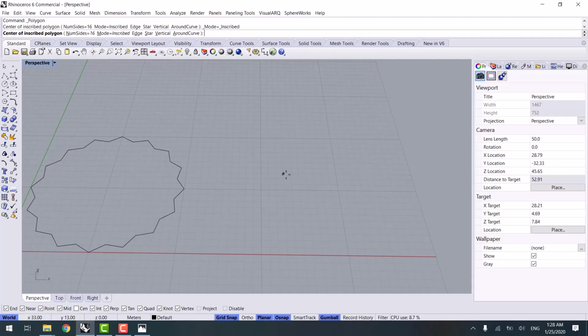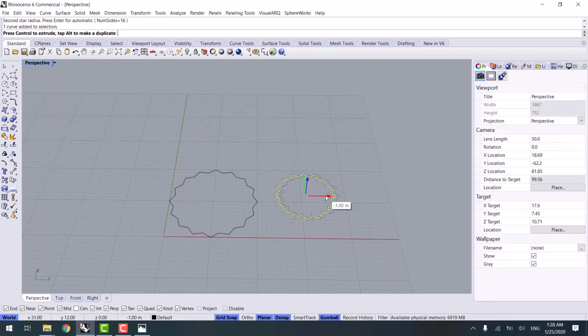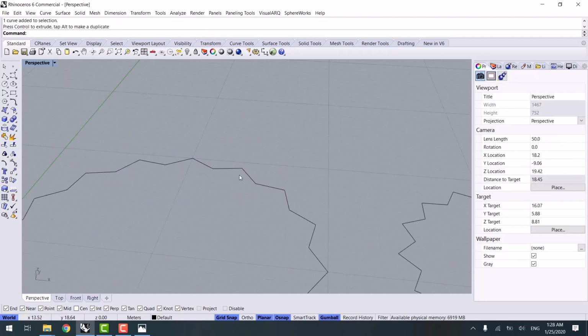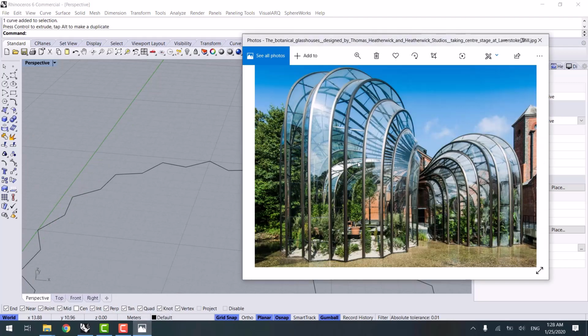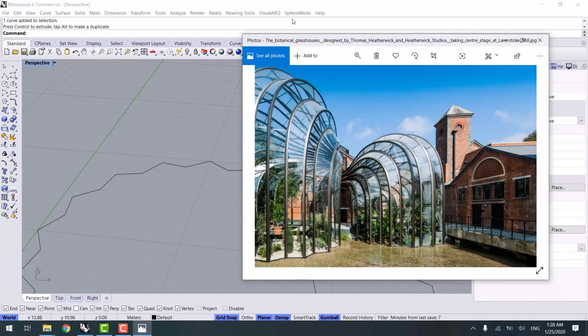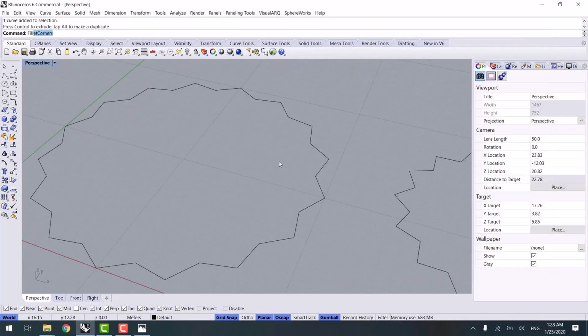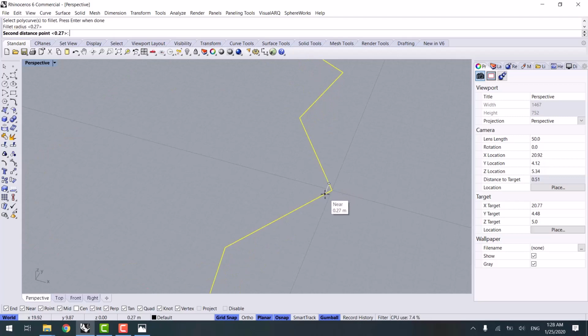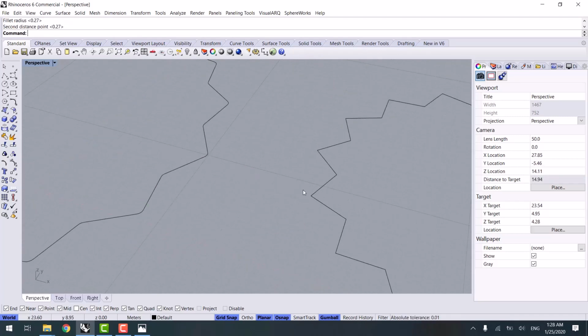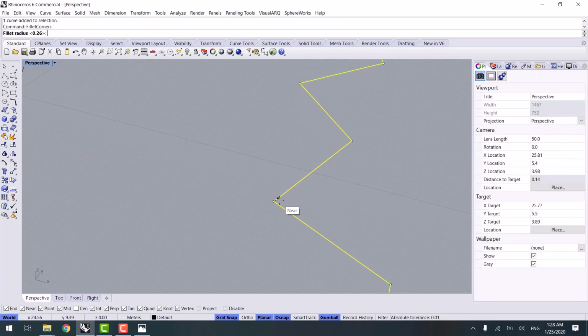And we want to draw something else, but a bit smaller. I click on star. Okay, and I put it here. And the thing that I need to do is to make these corners smooth, as you can see it in the picture. And here I use fillet corner and I draw a line here, and for the other one I say from here to here.